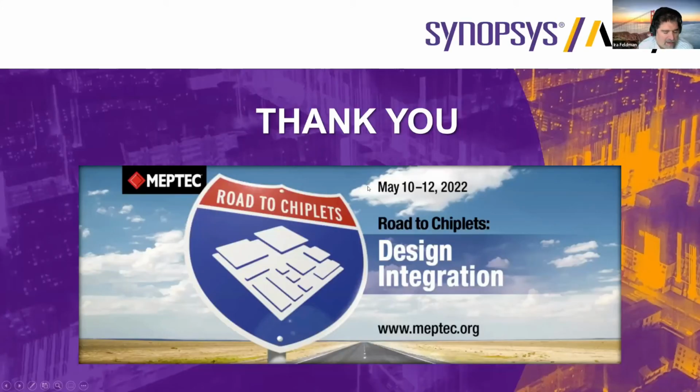Thank you, Kenneth, and thank you, Mark. One of the questions that comes to my mind is, when you're running the simulations, you often have to set boundary conditions and meshing and decide what symmetry you need, and that usually takes an expert to do. But are there areas where the tools extensively check things? Let's say like the pin heating, if you put a design rule in, will it automatically do that for every pin, or does somebody have to decide to do that? For the pin heating, there is a maximum setup, and it will flag anything that exceeds a preset limit.